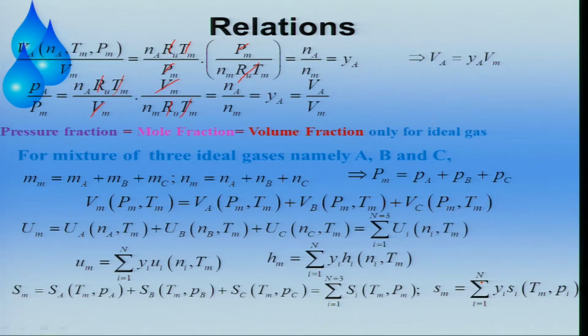And now, let us look at enthalpy, because we will be dealing with enthalpy, right. Let us look at enthalpies. So, the specific enthalpy of the mixture is given by the summation of X_i h_i with a cap. Keep in mind that this is enthalpy per kg of fuel. That means, enthalpy is in kilojoule per kg. This unit will be kilojoule per kg with a cap, and without the cap, that is kilojoule per kilomole. Similarly, for this case, you will have to use the mass fraction,